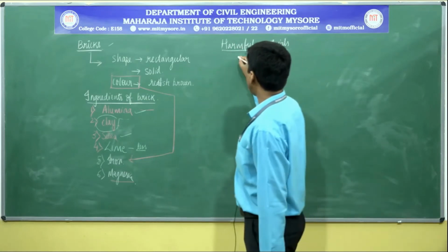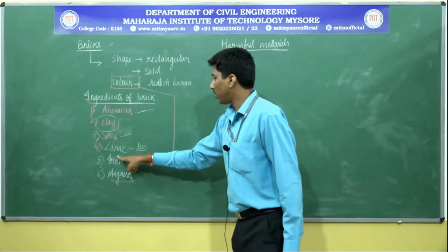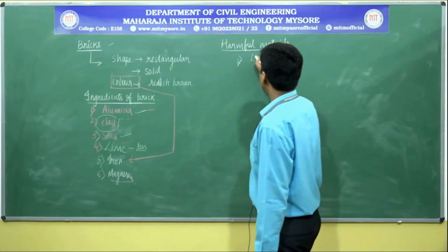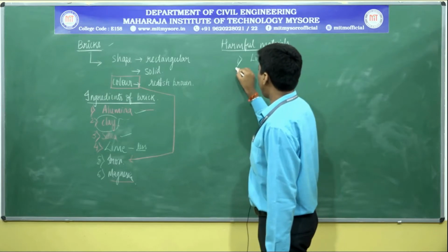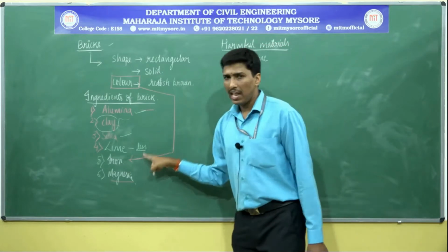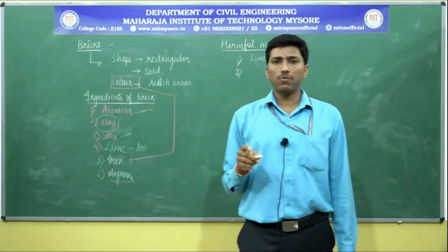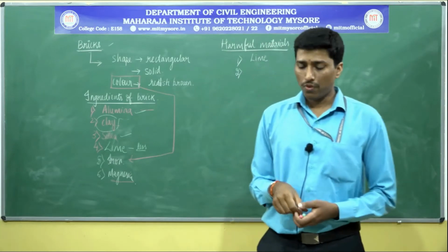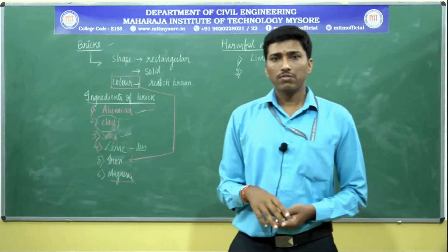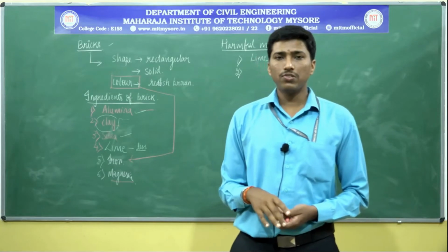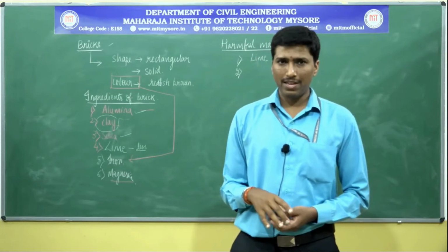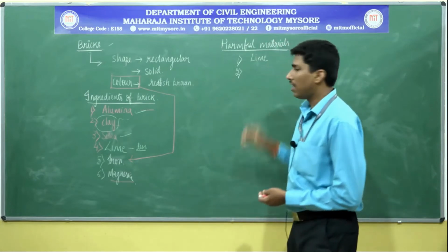Now, harmful ingredients: the first thing that comes to mind is the excess of lime content. As I already mentioned, lime content in excess quantities renders the formation of oxides, and it causes the bricks to break up easily. That is one condition.